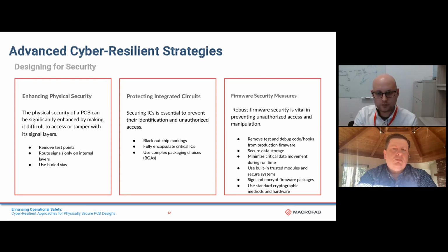When you're selecting hardware components, using vendor-provided trusted modules or secure storage is big. Like we talked about before, you can't necessarily prevent nation states targeting your device, but in terms of companies that have the resources to try and prevent those attacks, some of the large chip manufacturers who are providing the tools, those are things you should be taking advantage of. You want to, again, low-hanging fruit, sign and encrypt your firmware packages. You want to prevent malicious code from running on your devices.